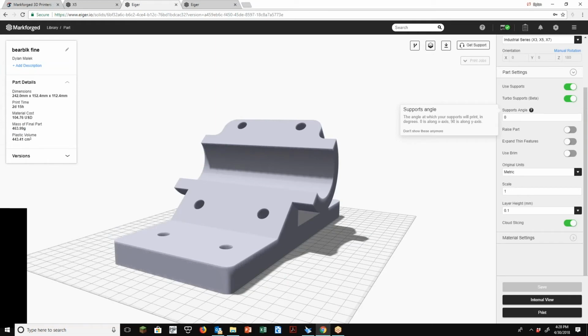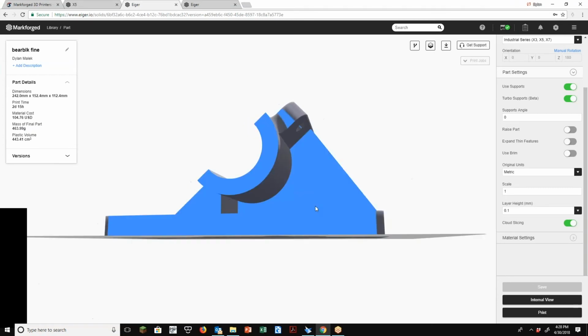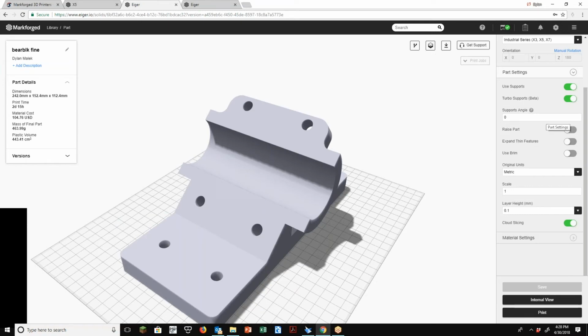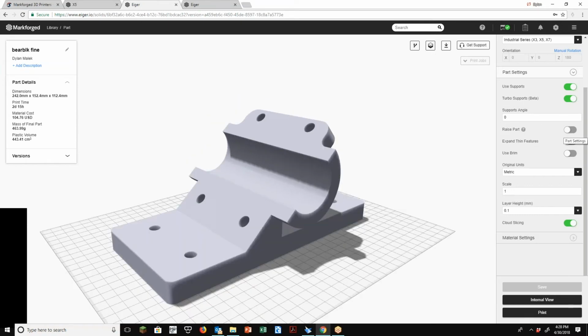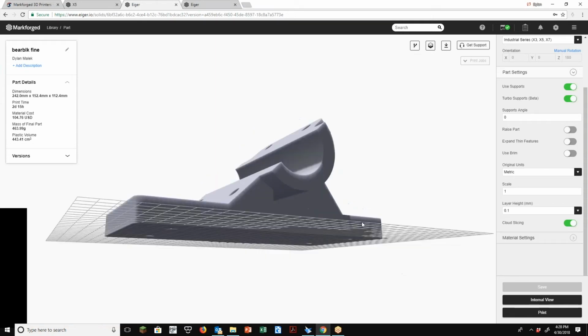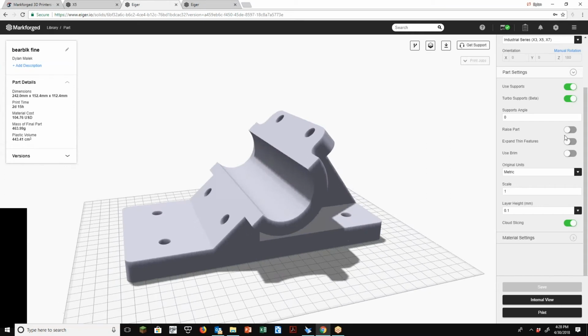And of course, if you wanted to adjust the support angles of those, again, it's relative planar. It's not the angle in Z. It is a more planar XY orientation angle. All right, raising part. A part like this is massive. It's got a lot of surface area at the bottom. I would never need to raise this, but in certain situations, if you had a part with some detail in the bottom and it's going to put support material in there, sometimes you want a little more support material so you can raise the part off the table. That way it gives you a little more support material to pull off the part, a little more purchase on the material, so you don't have to dig it out of small features.